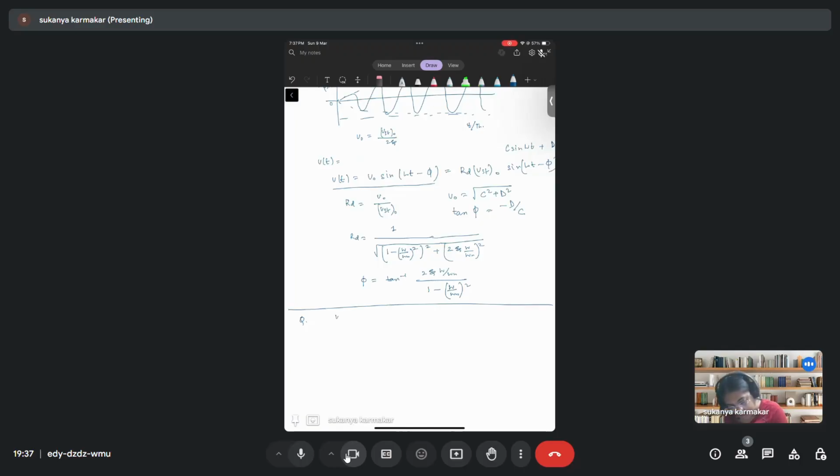It is known that when omega is equal to omega n, your u naught is equal to 5 inches, and when your omega is equal to 5 omega n, your u naught is equal to 0.02 inch. I want you to estimate the damping ratio of the system.